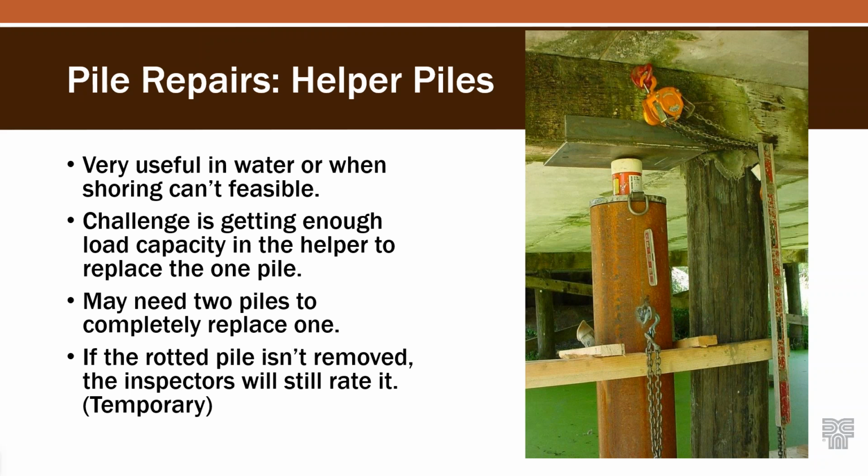The challenge with this is getting enough load. So what you can see here, and I'll run through a few slides of what it looks like for this one, is they're using a jack that's bearing up against the timber cap above it. And so it's basically using the weight of the bridge to push this pile down and get it into place. The problem is that the pile that was there originally is holding up not just the bridge weight, but also traffic plus the bridge weight. And so something that you might have to do with these piles, I've seen, is they'll actually park a loaded truck on top of this location, so you get that extra resistance to be able to use as you push that new pile down into the ground further.